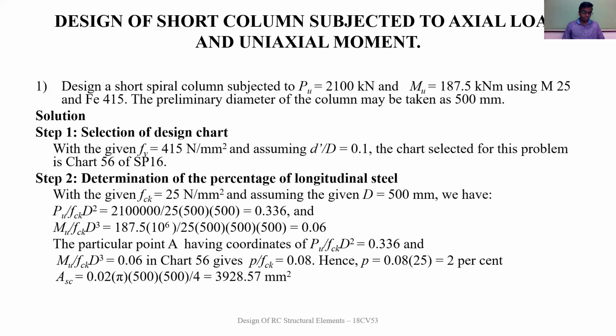Longitudinal bars in circular columns: though the design chart considers 8 bars uniformly placed circumferentially, it may generally be used for any number of bars greater than 6, uniformly placed circumferentially. These are some of the approximations that we need to know before getting into the design of columns.